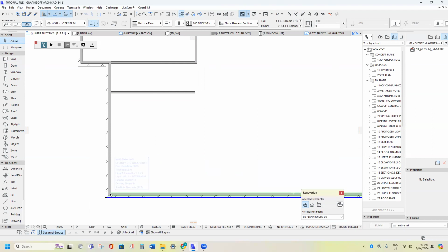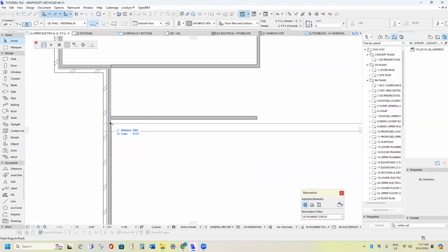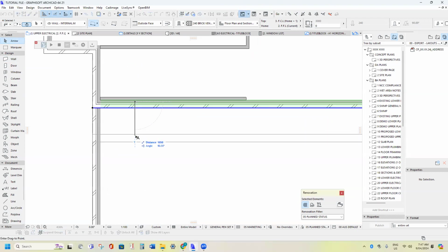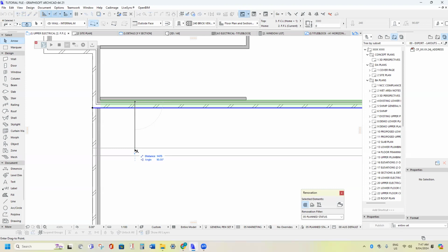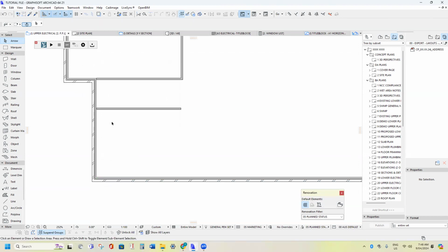Now I'm going to make a bedroom here, and we'll make this a master, so we'll make it 3.6 meters wide. So if I press Control D on that wall after I've clicked on it, and I click on the corner where the arrow is, then I can drag it over to that wall. See, it's 5320, that's a bit too big for the bedroom. So if I drag the wall over to there, and when you get the tick, you click, and then press Control D, hold Shift down to make it straight, press R, 3600. That's just a quicker way to get the bedroom size correct, and then press Control to trim off that part.